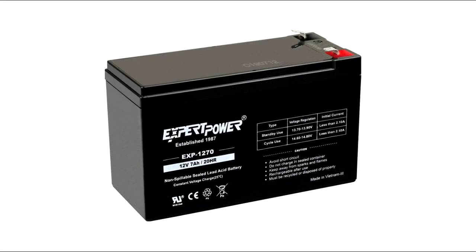The last part of this project is the charging of the battery. If there is line power available, a battery is technically not required. However, 12 volts will be needed regardless to power the solenoid and should have at least 6 amps. For this reason, using a battery would still be best. This would guarantee a clean, consistent, and correct power supply.